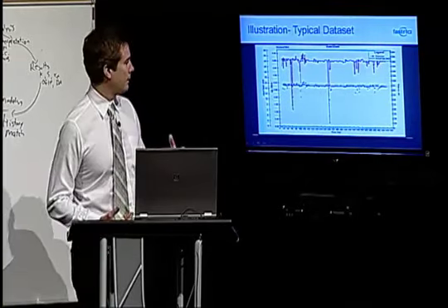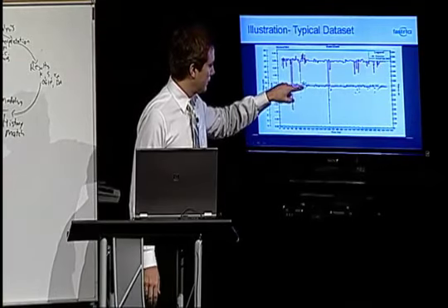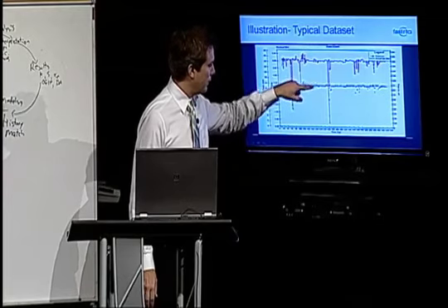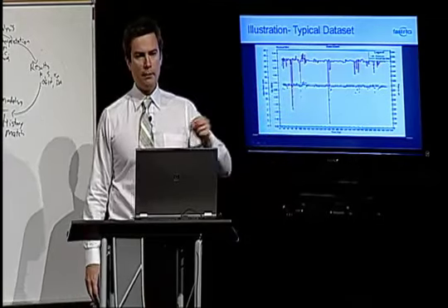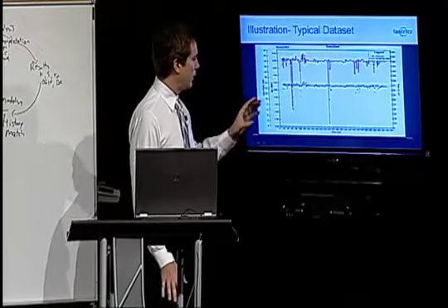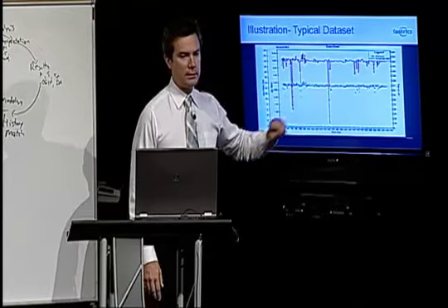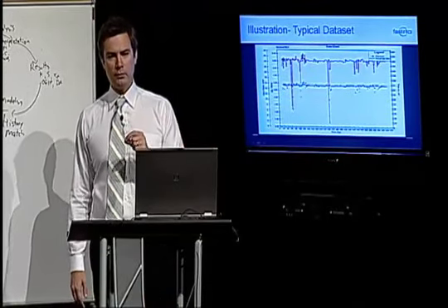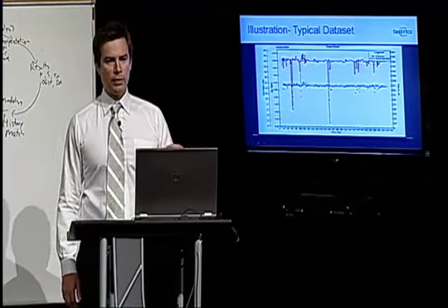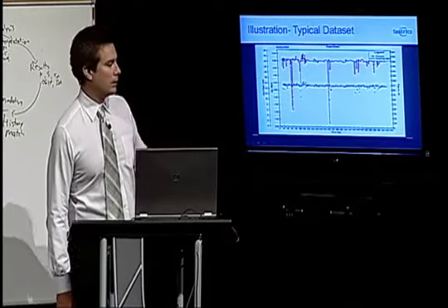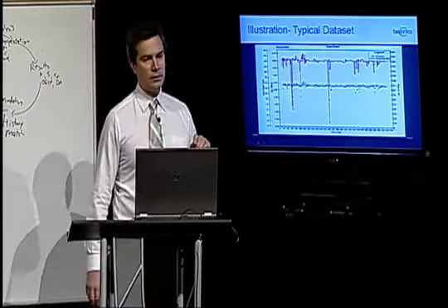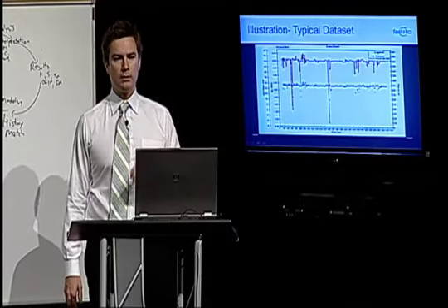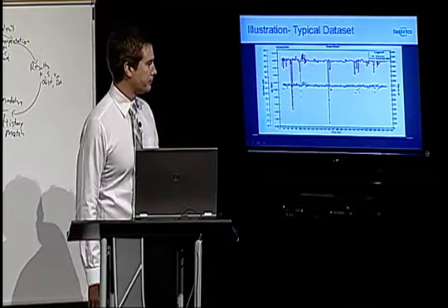It looks good in the sense that the rates and the pressures are changing continuously, which tells me that they're being updated very often. What I very often look for is a stair step. A stair step tells me that nobody's updating those rates or pressures. They're not being measured very often. So the measurement frequency here is not an issue. We're getting good quality measurements on a continuous basis.